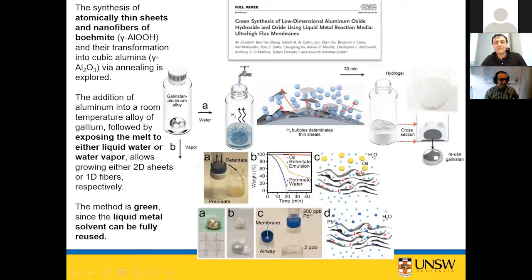The filters are for heavy metal ions, because aluminum oxide is known to absorb heavy metal ions like lead at very, very high concentrations. Also the distance between the planes is very small, so anything else like oil can be trapped between them. And we go from dirty water to very clean water very quickly. The flow rate is very high.